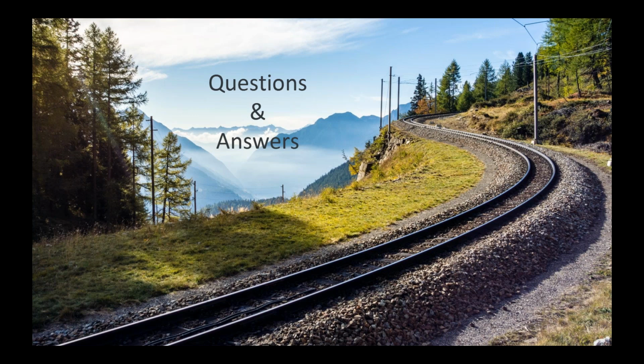Right. So in this simple application that we saw here, we didn't have that much interaction with wayside objects, but we had some very simple models, for example, for the point machines. When they were given a request to move, and that would correspond to an actual output from the interlocking system to the wayside object, then there was a simulation model causing this switch to actually move, simulating that it takes a few seconds to move this point machine. And it was sort of implemented as a program in the simulation environment.